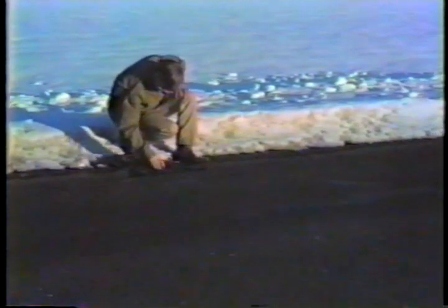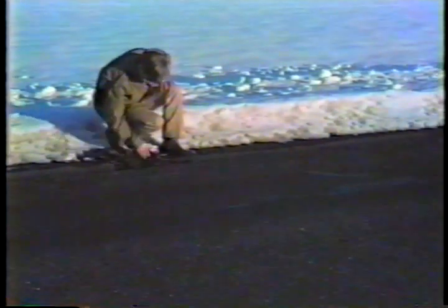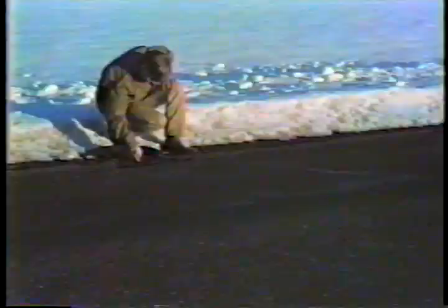Excavation of the base reveals that it is completely thawed to the top of the subgrade. Clearly, the base has little strength in this condition. The calculated thawing index as of February 6 was 26 degree Fahrenheit days, thus falling between the should and must recommended levels for a thin pavement.